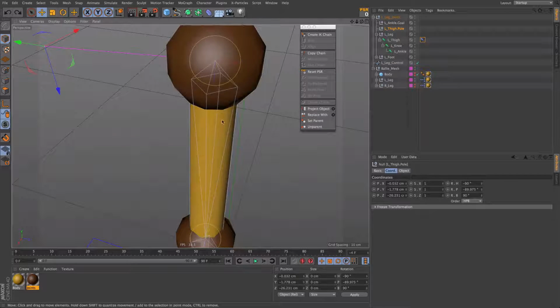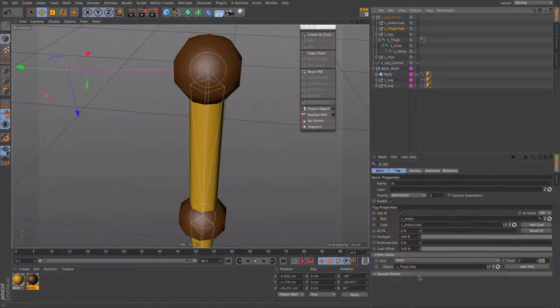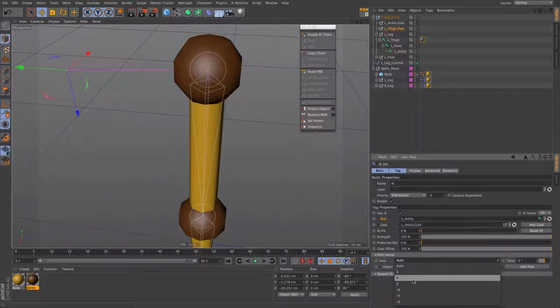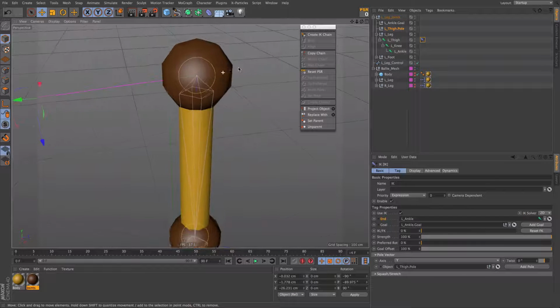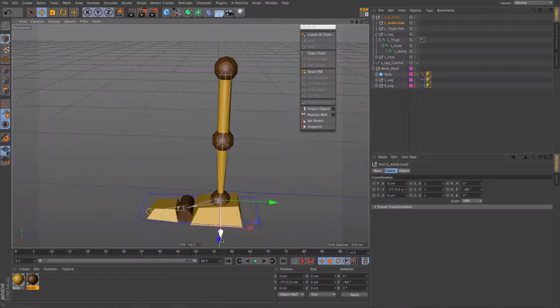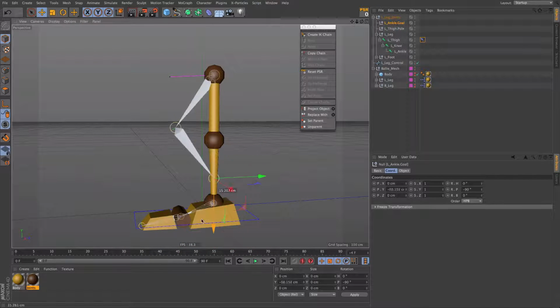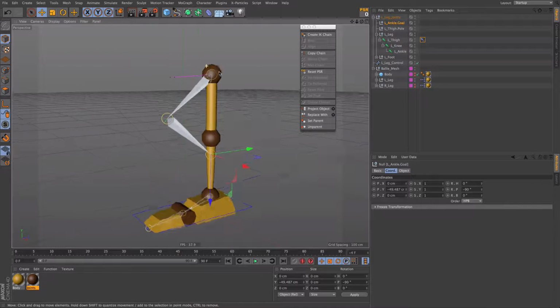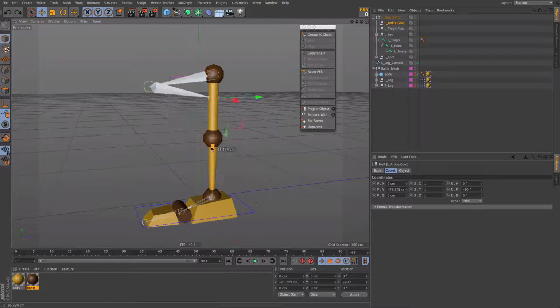You can see the axis of the joints. I'm going to change that. I'm going to use the y-axis as the banking because I'm used to this, and it's the default actually. If you draw the chain a little bent, it will be using its y-axis. And now if I move the goal up, you will see it's bending in the direction we want, but the foot is not moving.